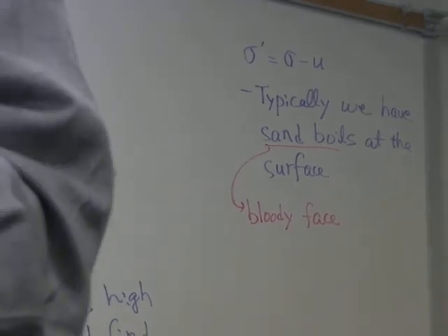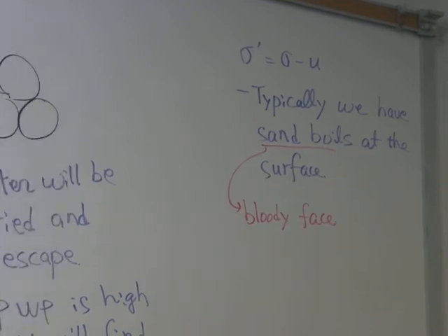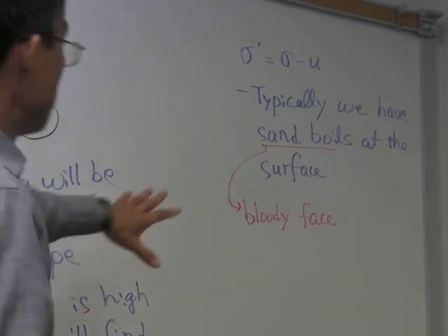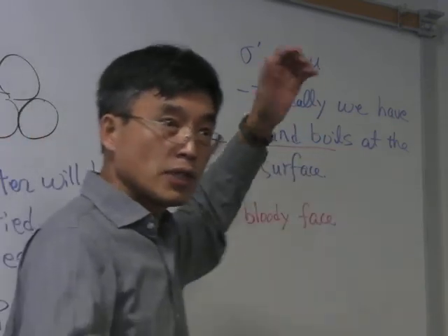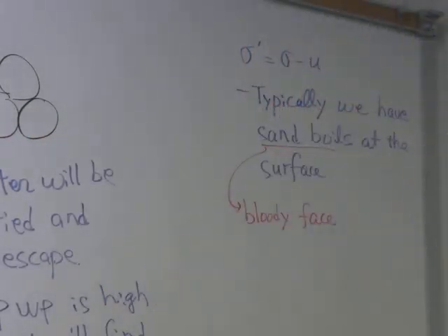When you have a liquefaction, that is usually somewhere, let's say 5 feet down there, 10 feet down there. We don't see it, but at the surface, we usually have sand boils. Probably Nathan remembered why we went out to the field to find out some of the sand boils.